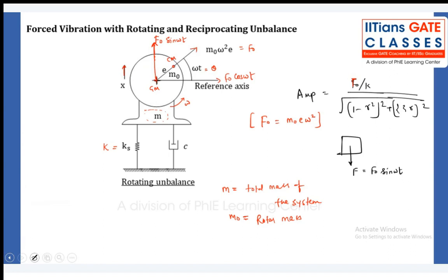Why is there forced vibration? This is the reality. When the machine is static and not running, nothing called vibration is there. Once the motion starts, every problem starts coming. And when this vibration is too high, the fatigue life of any component will become very small.